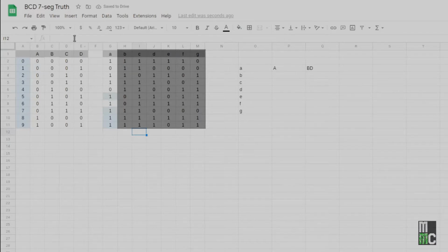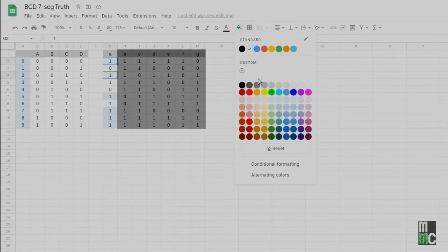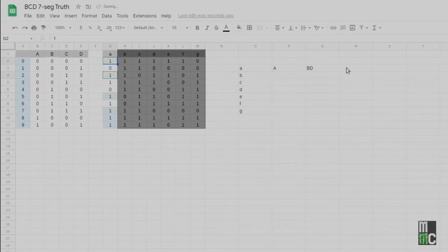And then we can also look at the same thing. I have the same thing going here when I don't have B and D on. I have a 1. If I follow that through, I don't have 1 there. And of course it's going to be this one here too, but we have a 1 there too, so it's fine. So what I want to do is anytime that I don't have B and D on, I get these 2 taken care of. So we're going to make that a yellow in this case, and then we're going to say not B, not D.